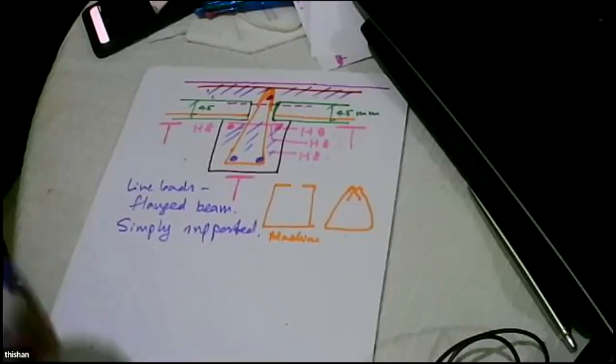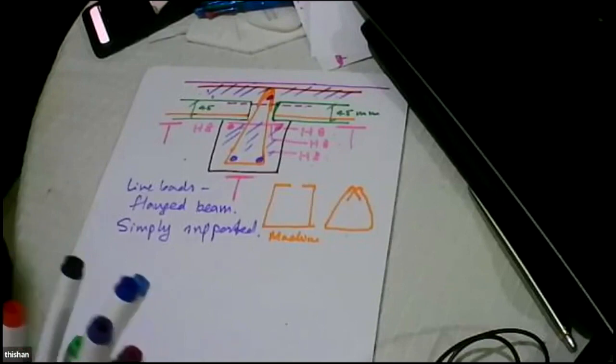So we can reasonably say the dead loads, live loads, everything will act on the completed structure, but not on the precast members. So we can design the system for the final situation. Can you understand that argument, Bandukha?